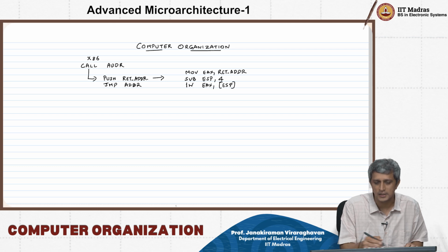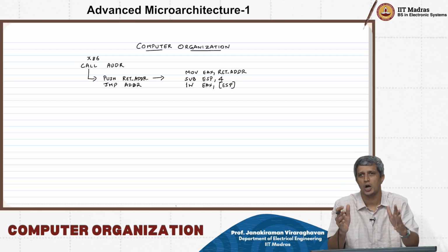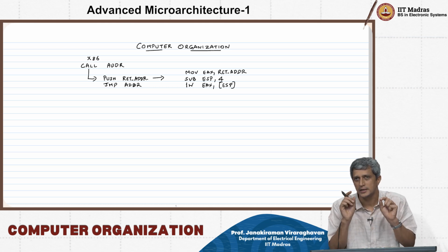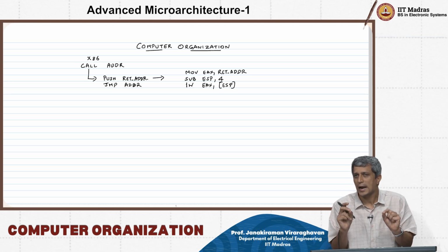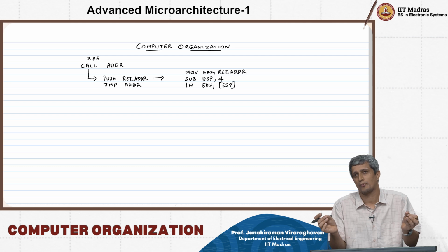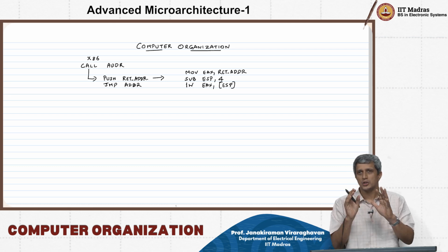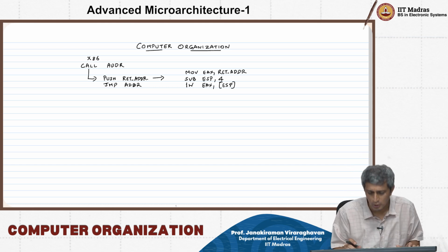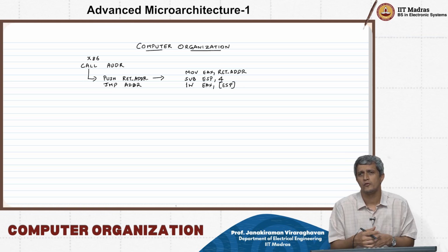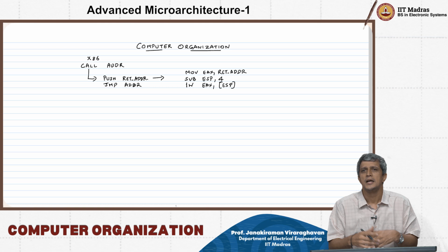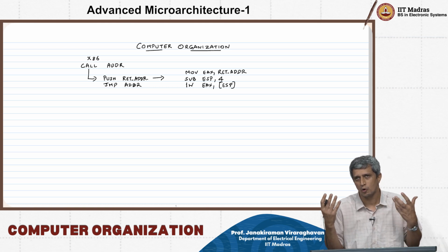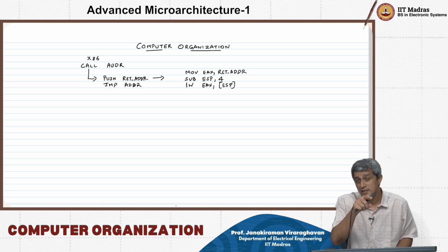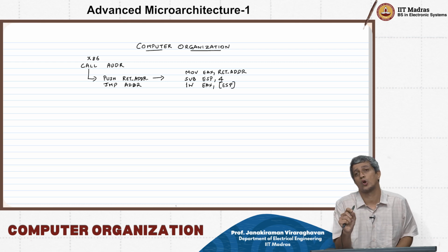So this actually seems to be 4 instructions in one shot that are happening in the x86, and of course all of this is implementable and practically usable only in a multi-cycle processor, not in a single cycle processor, right? So in the multi-cycle processor, you are doing like 4 instructions. Now just think about what you should do if you are to do this in a RISC-V. It's a very complicated set of instructions that is going to be needed, and specifically when you go from multi-cycle to pipeline processor, it becomes even more complex, right?